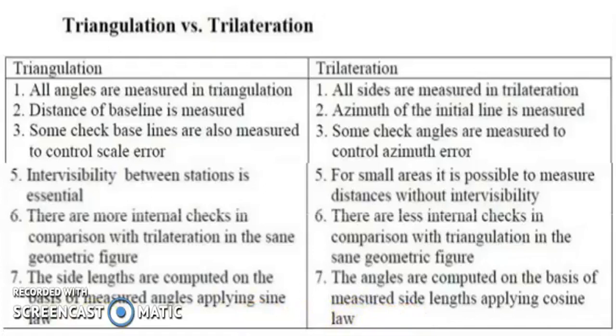Fundamentally, in case of geodetic surveying, we are more concerned about triangulation. Why? Because a geodetic survey is mainly established using triangulation, or it's also called precise traverse. Okay, we have a system of interconnected triangles. There are various guidelines for forming this kind of triangles. Most of the triangles are on a baseline. Okay, the main line is the baseline, and the measurement of angles is done very precisely in case of triangulation. Then, knowing each of the lines and the angles, the lengths of other sides will be computed. It's a basic trigonometrical thing that we learn, right?